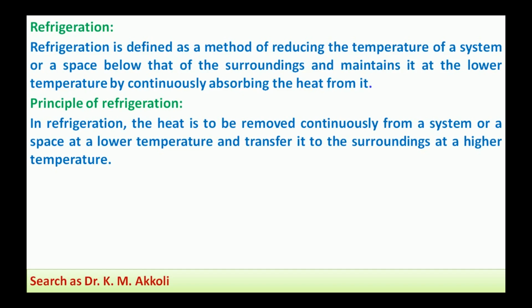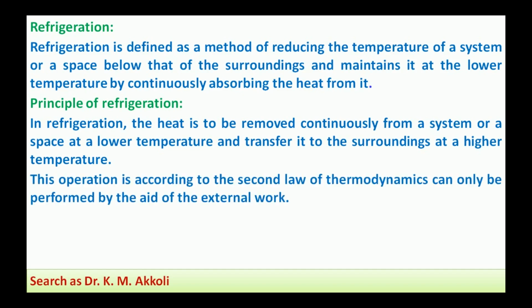And for that, what is required? As per the second law of thermodynamics, this operation can only be performed by the aid of external work. The second law of thermodynamics states that heat cannot be transferred from a lower temperature body to a higher temperature body without external work. For this operation of refrigeration, external work is required to transfer the heat from the lower temperature space or system to the higher temperature space or system.